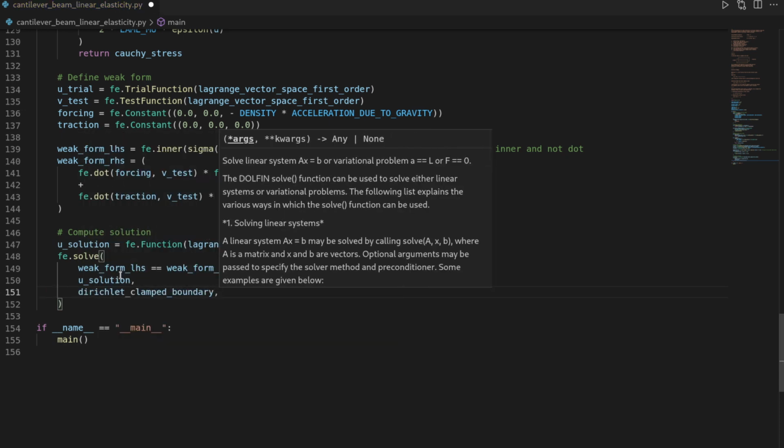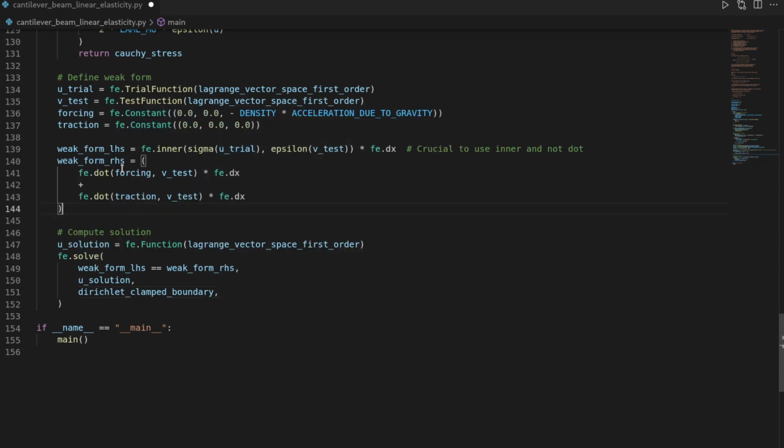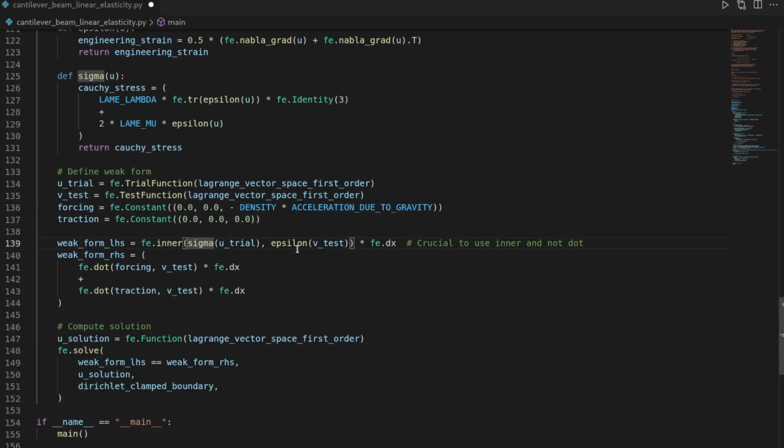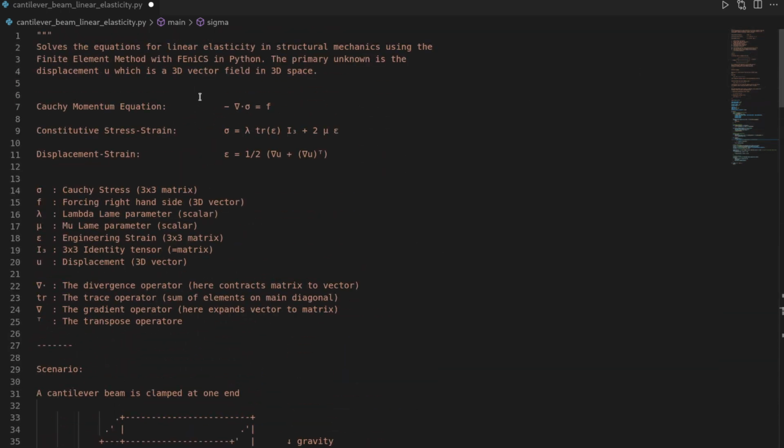boundary condition. And what FEniCS is going to do under the hood is first compile our weak form, because there are some nested expressions: we have this function call to sigma, to epsilon, and then within sigma we have a call to epsilon. So in the end, the FEniCS implementation will compile down this weak form, and in essence will do what we could have also done by just inserting all the nested dependencies into the momentum equation.